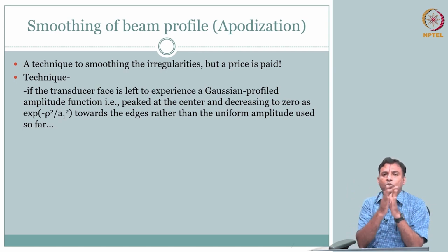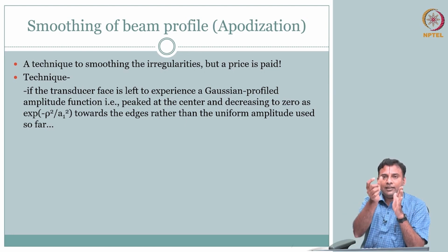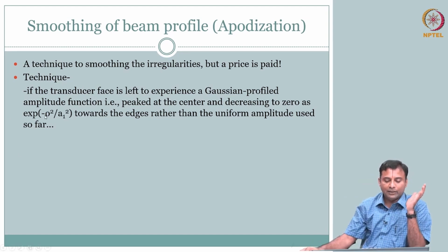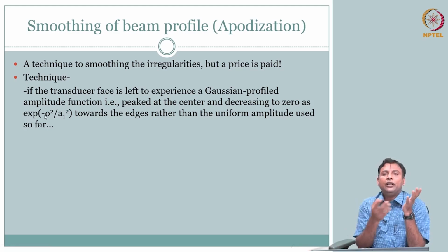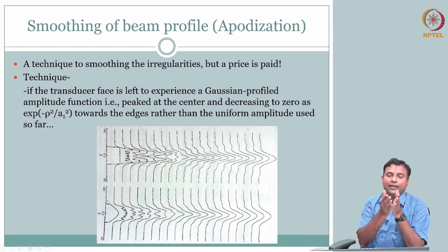So, you could come up with a material. Basically, this is sound. I want only the center to contribute, and the sides to contribute less. So I can have a sound absorber, more sound absorber at the corners and less sound absorber at the center, and I can have a profile of that. It can change from no absorption to high absorption in, for example, an exponential fashion, which is kind of your windowing. So instead of this rectangular, I can profile it. I can come up with a material, say a sound absorber. That is an easy one to visualize, at least for you.